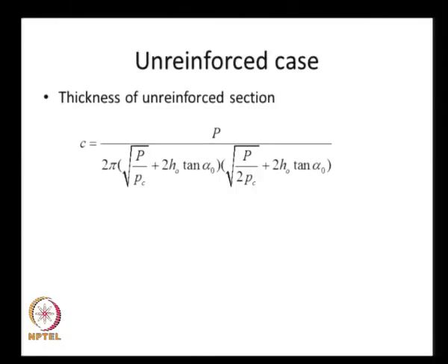So, this is the same relation written in a slightly different form, and here if we know the C, that is the cohesive strength of the subgrade soil, and the wheel load P, we can calculate h naught.